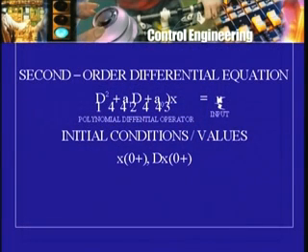Transfer function is a ratio of Laplace transforms. It is not a ratio of output to input. Now, when the differential equation was simple like this, the first order or the second order differential equation where there was only a u term on the right hand side, the transfer function, I told you, could be written down immediately without going through this business of applying the Laplace transformation to the two sides. What if the differential equation is a little more complicated?